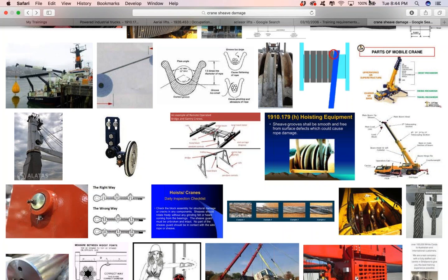All right. Now, this is the thing, folks: we have to have a spotter during crane operations or even moving a crane. Anytime we're moving a crane or doing an operation, if we lose communication with the spotter, both visual and audio, we have to stop exactly where we are until we resume at least one of the two types of communication. That applies whether we're in a crane operation or a crane movement.